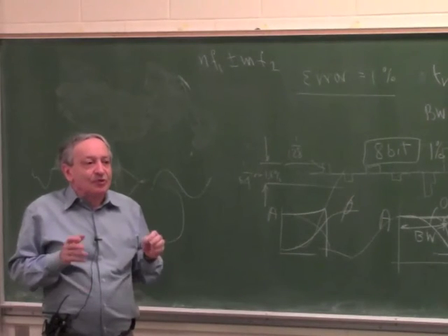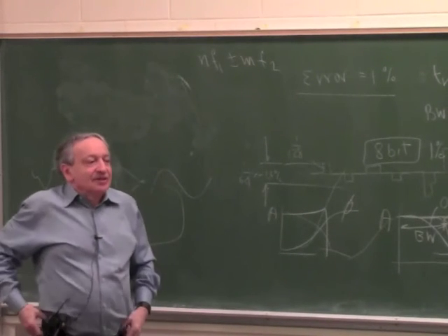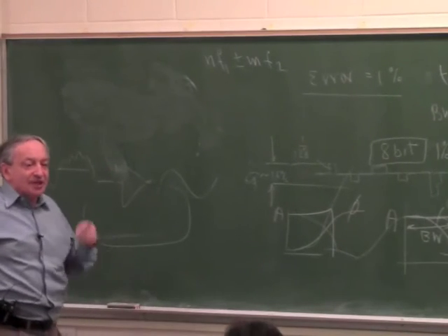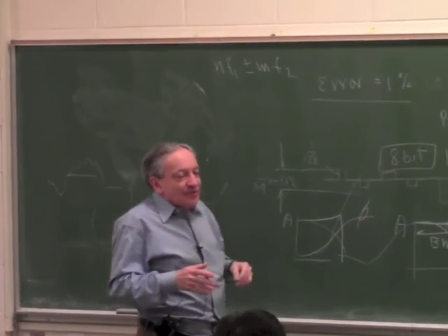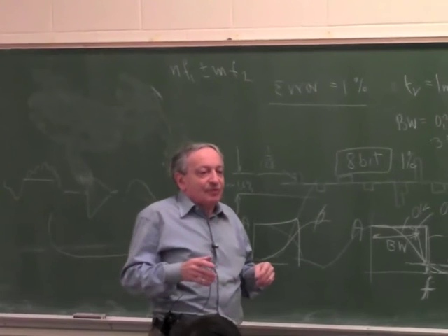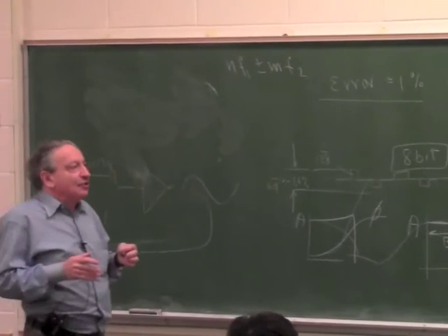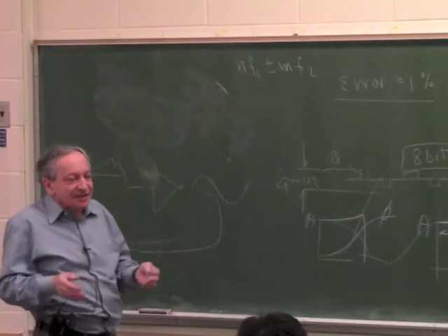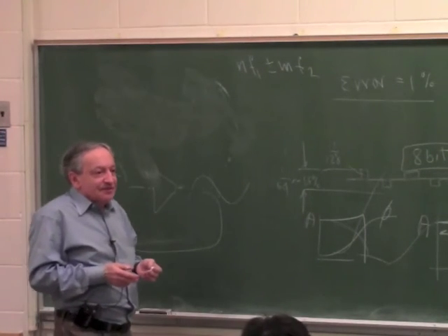Because you have to know when to use the average, when to use the RMS, right? It depends what you're trying to find out, but the main thing is if you're worried about heat limits, steady state limits, you have to use RMS.